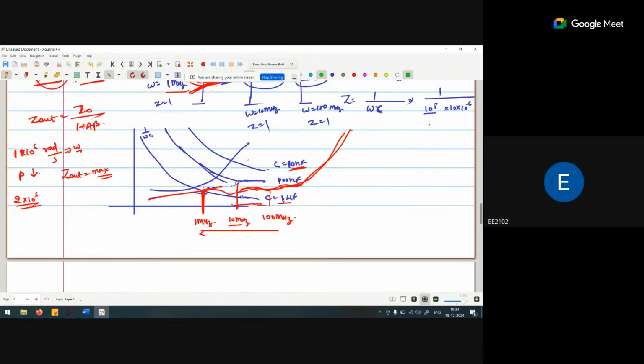So if I am saying that this particular capacitor will be lower at this frequency, and after that it will have an effect, after it will start increasing. But when it starts increasing, again we are getting a 100 nanofarad capacitor, so again it starts decreasing. After that it will start increasing, but again we are getting a 10 nanofarad capacitor, so it again started reducing, and after the 10 nanofarad capacitor there is no more capacitor, so it will start increasing.